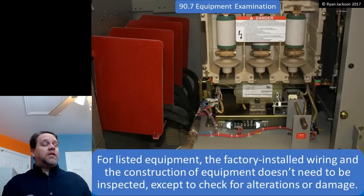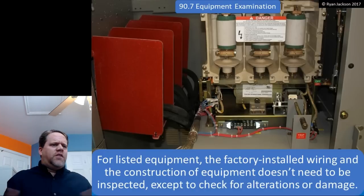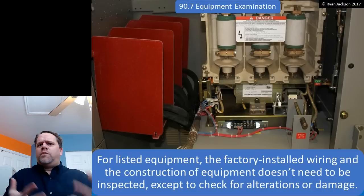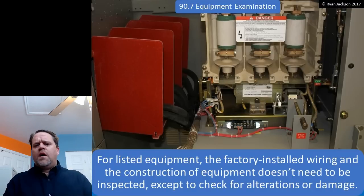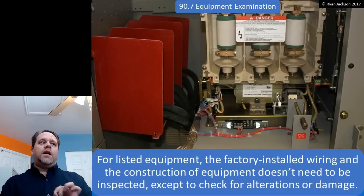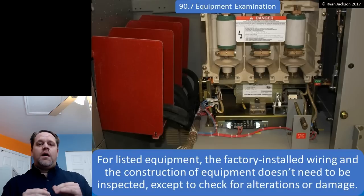Yeah, to an extent. You just can't damage it. You can't change the functionality of it. You can't turn it from this into that, make it do something it was never even intended to do. So we have listed equipment, and then the AHJ is going to look at it and determine whether or not you altered it, changed it, damaged it, and if you did, then the AHJ is going to determine whether or not it's still going to be acceptable. So they'll look at the alterations or damage as a basis of